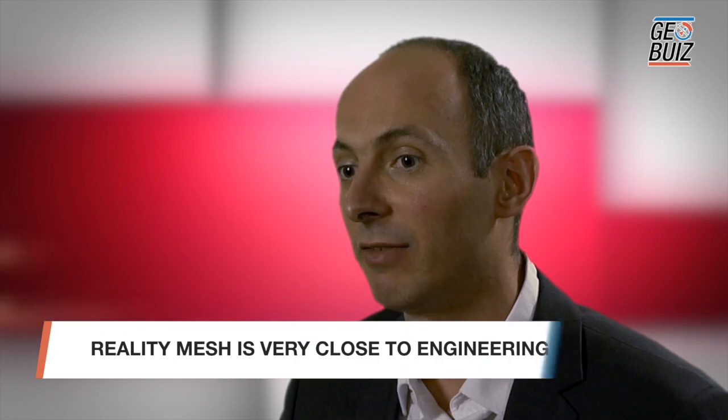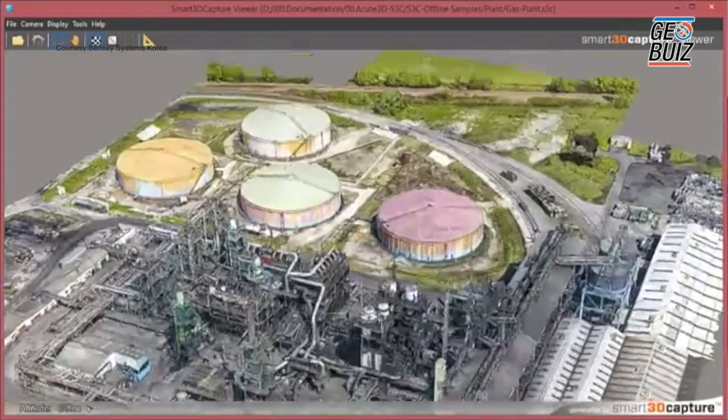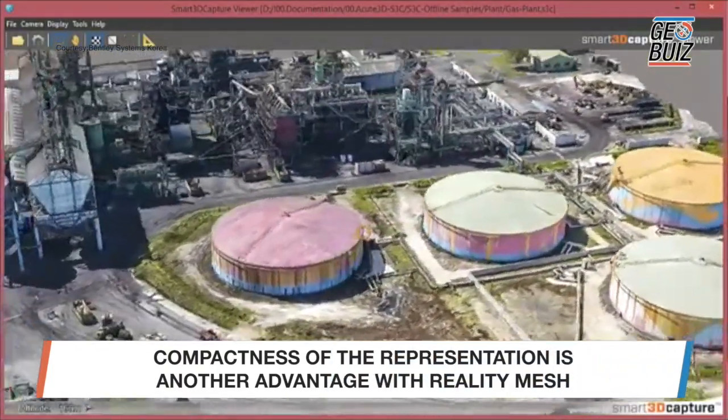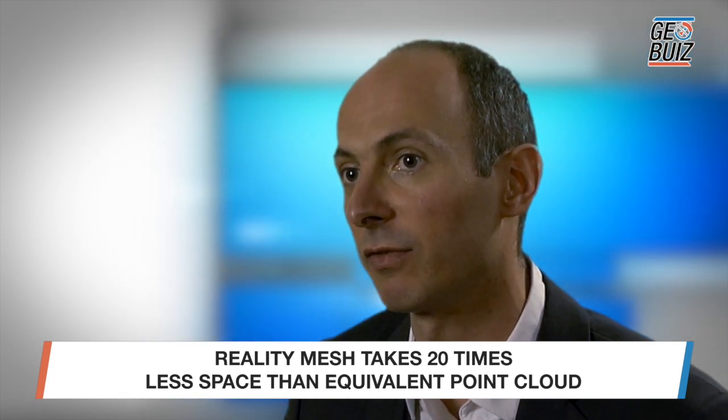How different is the reality mesh from the typical point cloud? Reality meshes have a lot of advantages. First, they are closer to the engineering models that you typically work with. Second, they offer a more immersive user experience than point clouds because they are very close to the 3D models used in video games or for movie visual effects. Third advantage is the compactness of the representation. A reality mesh for the same precision typically takes 20 times less space than an equivalent point cloud. So we save a lot of storage space by using reality meshes.